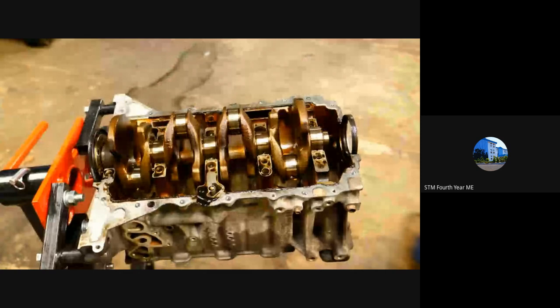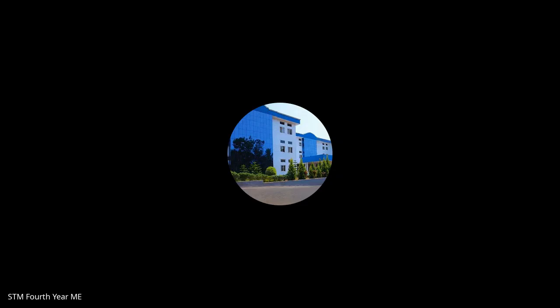So the crankshaft is here, with crank pins for each cylinder. Main journals are also present. These are the holes for lubricating the crankshaft, and at the crank pins there will also be holes for lubricating the connecting rod. So these points are the journals here.